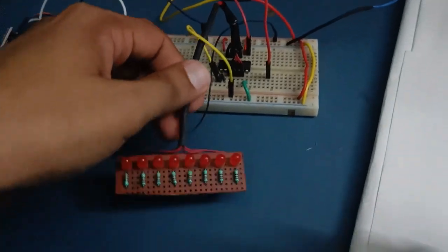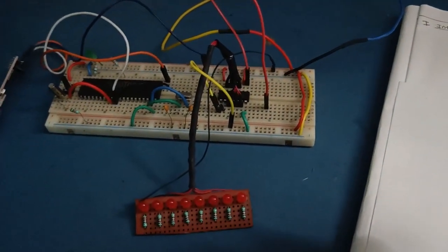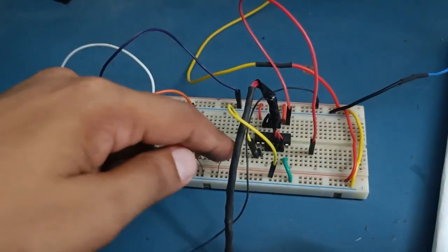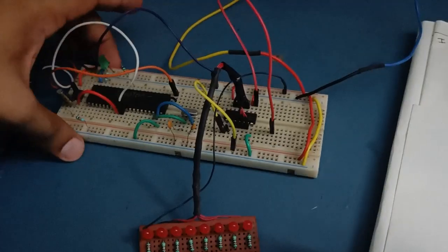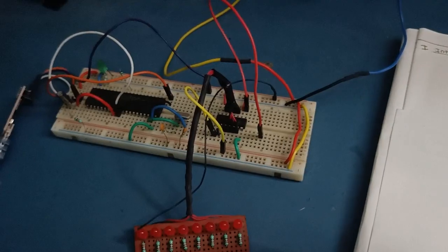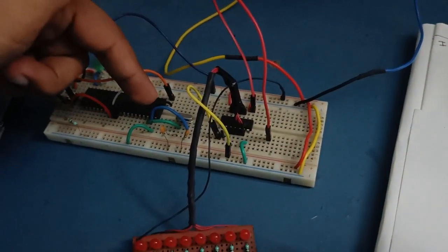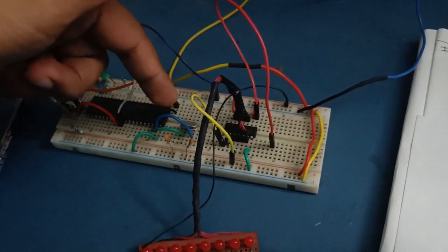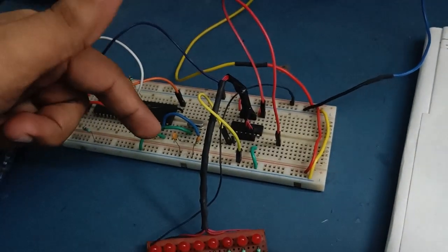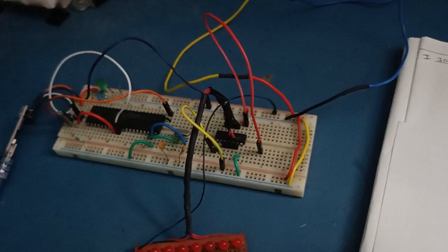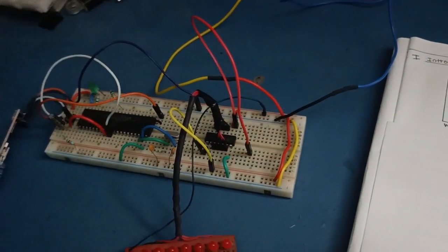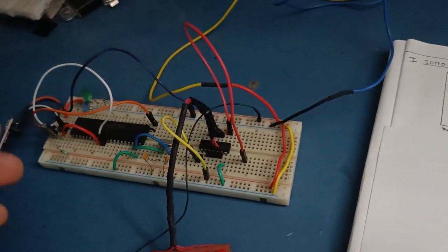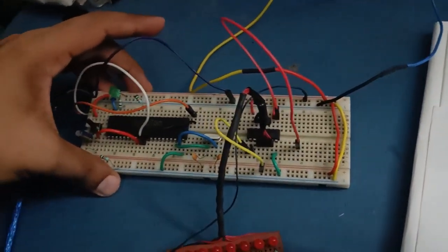This is a shift register with LEDs so that I can show you how mode 0 works. The crystal oscillator I am using is 11.0592 MHz along with 22 picofarad capacitors. Watch the beginner's guide video, link is in the description. But in that video I am using a 16 MHz crystal along with 47 picofarad capacitors. So make sure you replace that with an 11.059 MHz crystal along with 22 picofarad capacitors, because using a 16 MHz crystal messes up the baud rate calculation only when we are using timer 1. But when using timer 2, we can use 16 MHz. So we'll see how to do that.